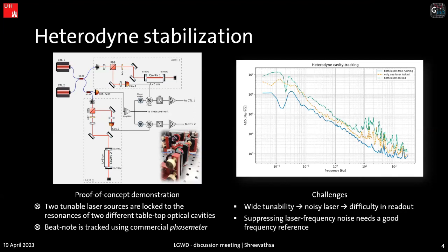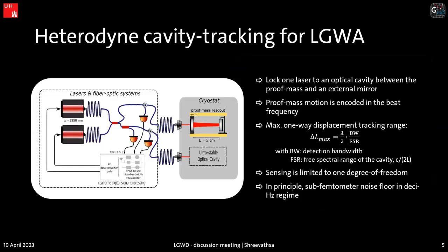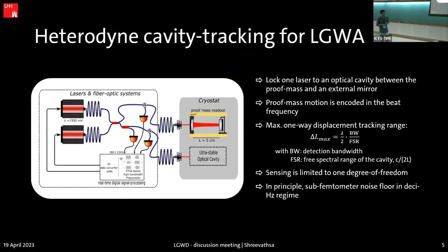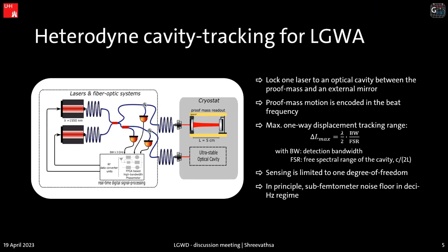Not large range. I mean when the two masses or the reference displacement you're trying to measure are across largely separated bodies. If your bodies are very close by, for example, in the Watt linkage, your moving mass and the reference frame are very close by, a few millimeters or few centimeters apart, how does this technique compare in terms of the residual noise? Techniques like capacitance sensing or evanescent sensors can measure small gaps. They are not good for large separations, but for small gaps for the Watt linkage, probably they can be competitive.